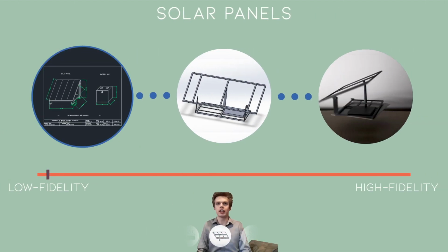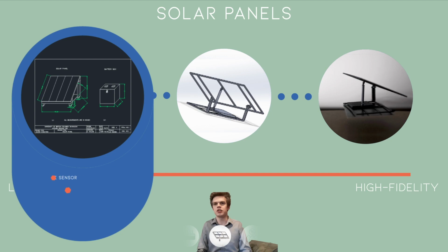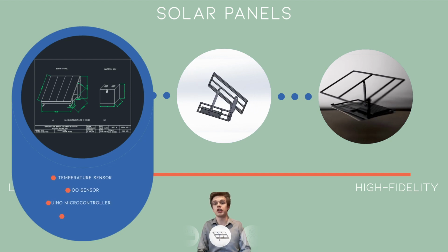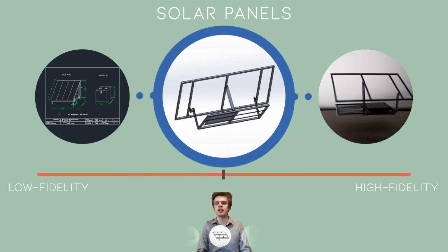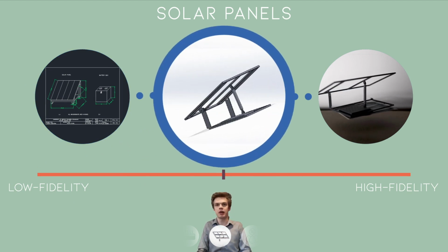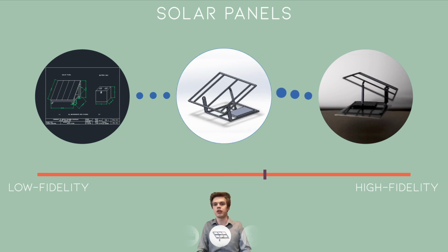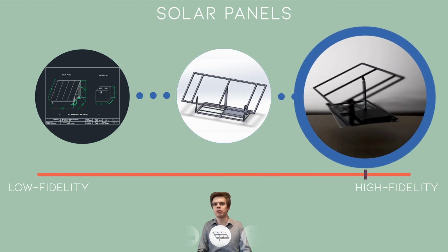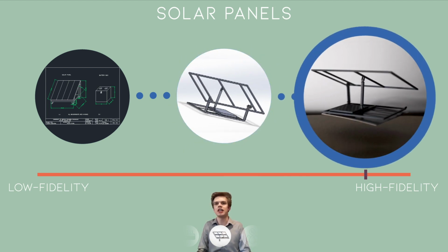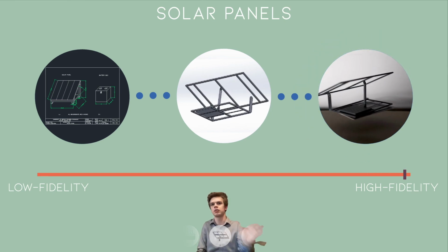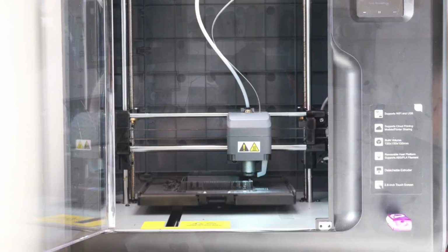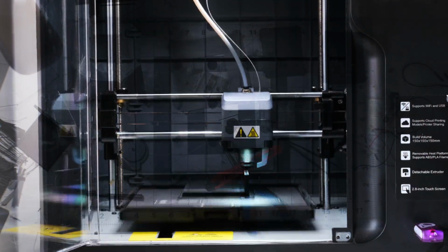There are 4 separate electrical loads: the temperature sensor, the dissolved oxygen sensor, the Arduino chip, and the air compressor. The main source of power is the solar panels. However, there is a backup battery system for when there is no sunlight. The battery is capable of powering the whole system for 20 hours, and the solar panels can recharge an empty battery within 9 hours. And after the hours of work our team has put into Project Pond, this is what it would look like.